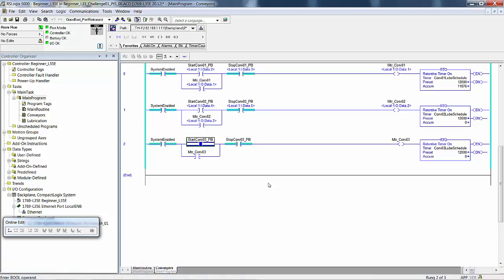Okay, looking here, if I turn on input 2 and input 4, and this one I can't hold on because remember I have that temporary logic that turns it on and back off. But in the manual it asks you, do the rungs look true? Do these rungs right here look true? This one and this one, 0 and 1, do they look true? Yes. Is the logic setting the output bits to the on state? Well, does it look like it? No. Are the timers accumulating? No. Just for grins, I see some data table carnage there.